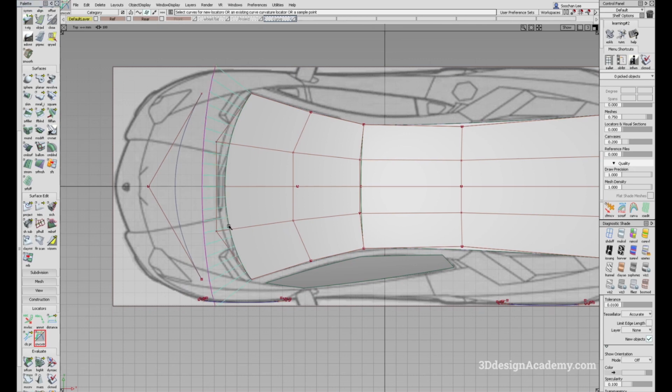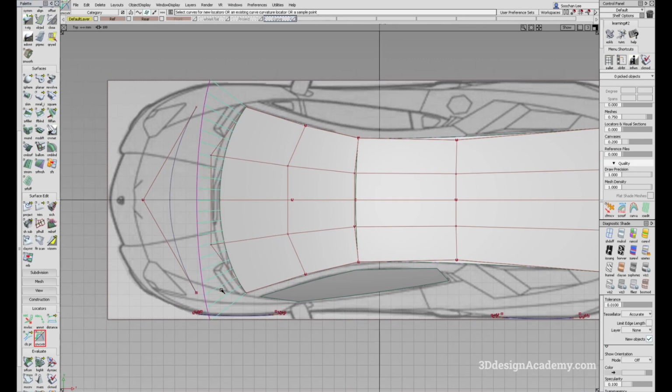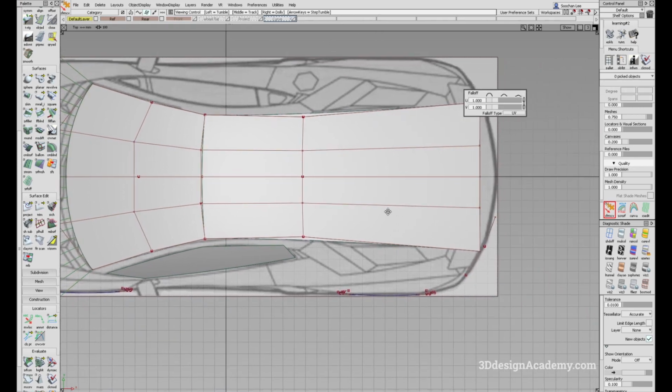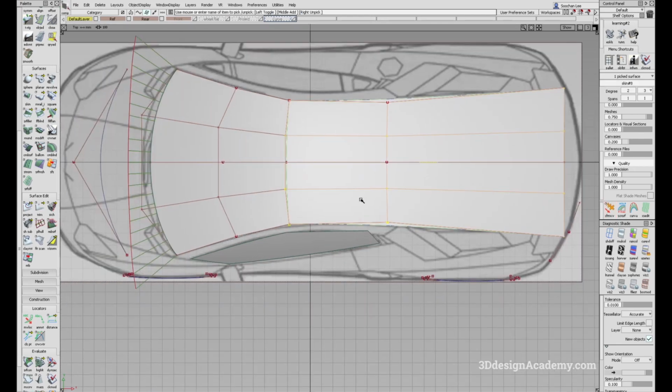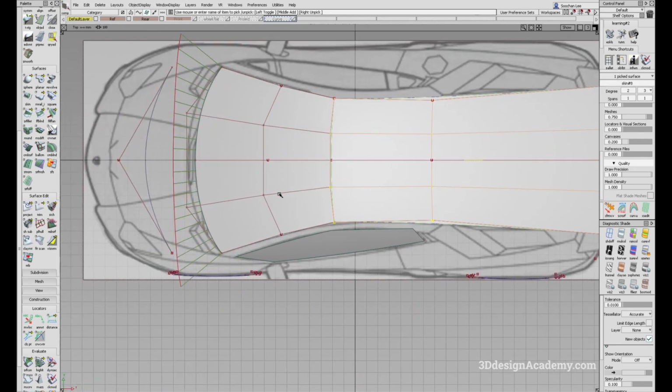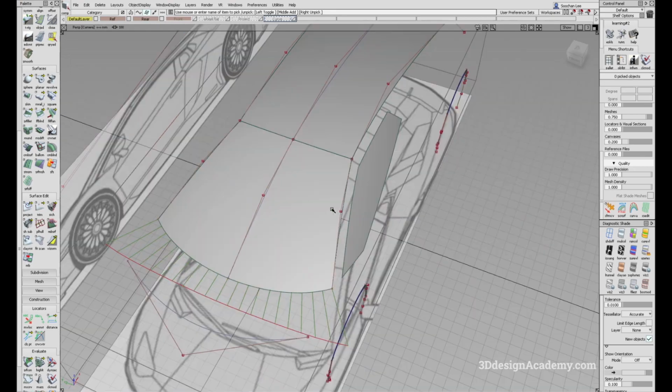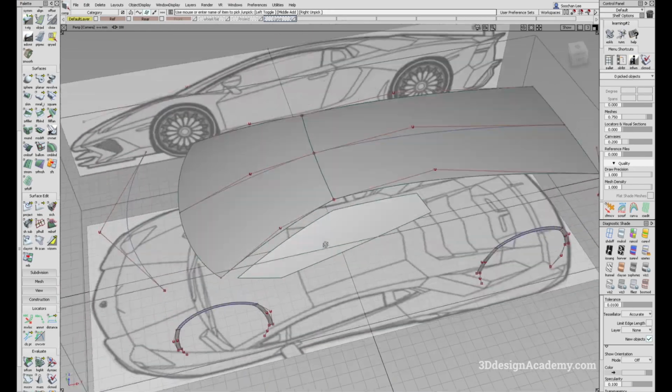And let's check the curvature. So we got a little bit of acceleration towards the outboard side. Now this looks a little bit weird. I think it's partly due to how the CV and the shape is structured, but it's fine as long as we give it a little bit more acceleration towards the front or towards the outboard side. I think it should be good. Okay, so I would say that's good enough. And let's do the, well, actually this one I'm just going to leave it because this is just a prep surface for later. Okay, so I think that looks pretty good.